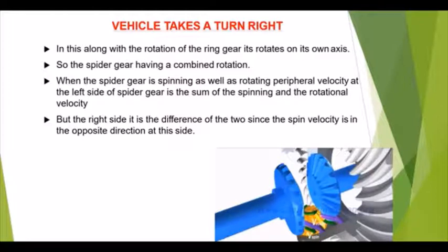This bevel gear meshes with your two neighbor gears, which rotate counter to each other, and it does not mesh with each other. This chain of spider gears is aligned on the same axis as the ring gear, and it drives the half shaft which is connected to your vehicle's driven wheels.